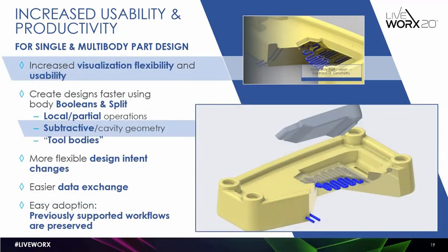In addition, you can easily design and optimize subtractive geometry in the part context using multi-body concepts. This is beneficial in applications and use cases such as in the design of hydraulic manifolds or fluid cavities in general. You can create solid bodies representing cavities or subtractive geometry in general in your design, and then use the Boolean operation body subtract to get to the final geometry. Let's have a look.